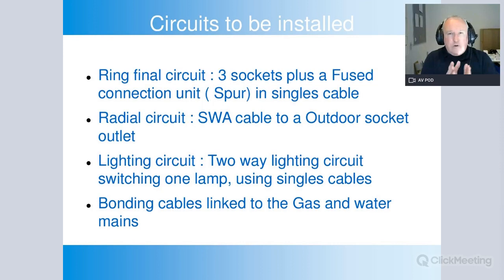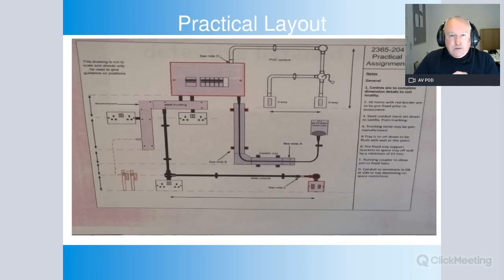If you look in your house or flat, wherever you live, under the sink or where the gas meter is, you'll see a bit of green cable, quite a thick green cable called bonding cable, like this. And it's attached onto that. That's to sort the earthing out, the equipotential bonding, which we're going to be doing a whole other lesson on earthing.